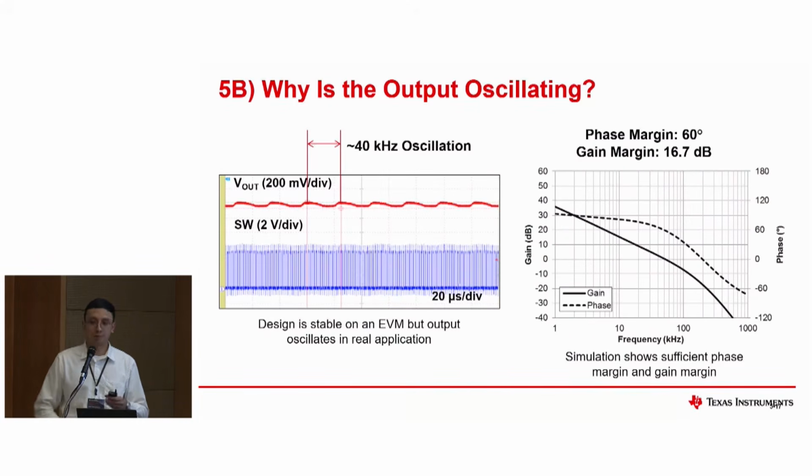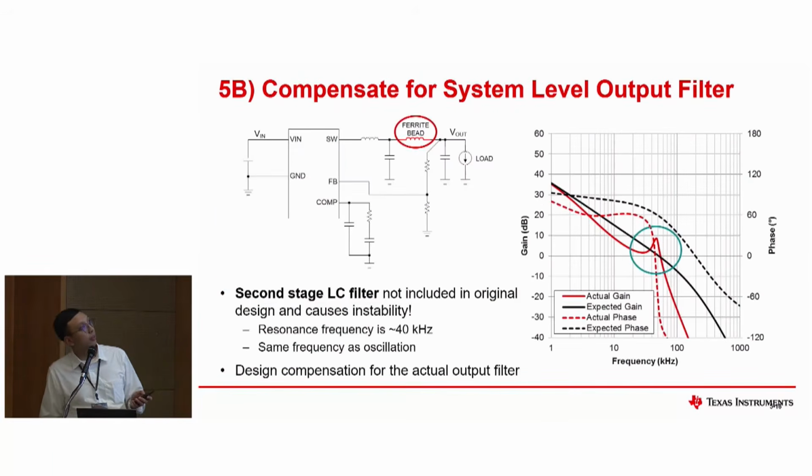Oh yeah, that can definitely be considered also there. Actually, for this situation, when they designed it on board, they added some additional filtering on the output. They added a ferrite bead on the output and a capacitor for additional filtering on the output pin. This caused a second stage LC filter that caused some instability in the design.